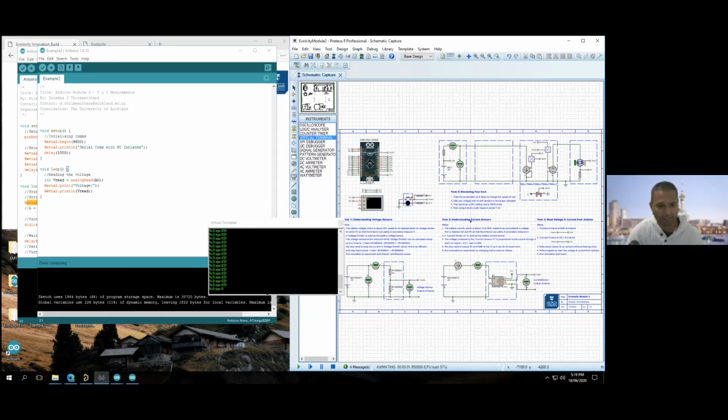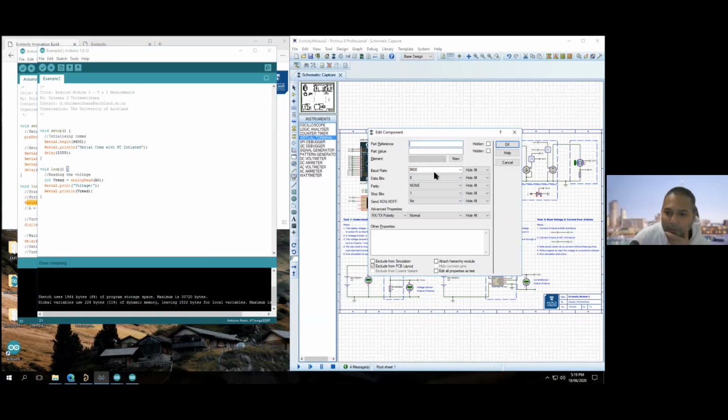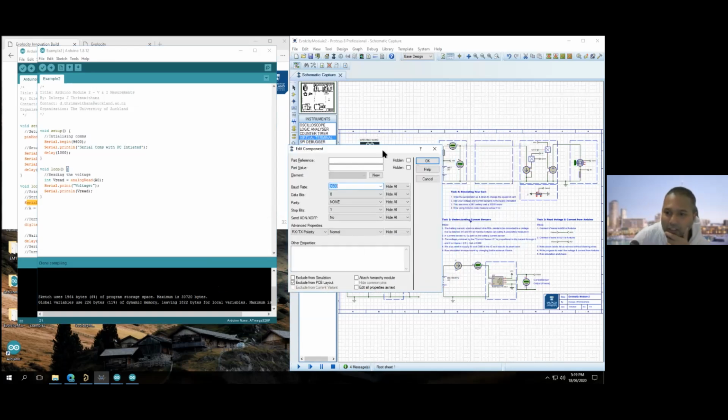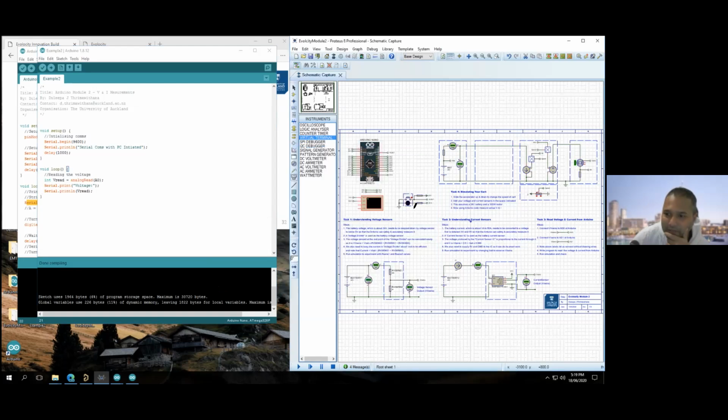My one, once again, isn't printing to the terminal. It isn't printing anything, in fact. Can you double click on the terminal and make sure it's 9600, none, 1, and no? Do you see the terminal? Yep. Are you using the code program that you downloaded from the internet, or your own one?